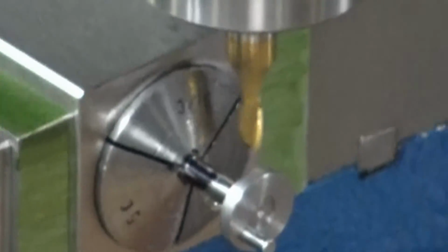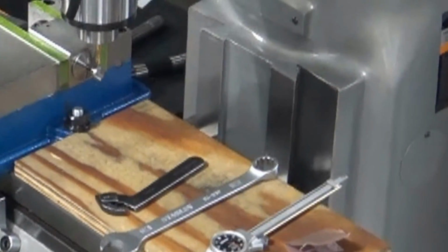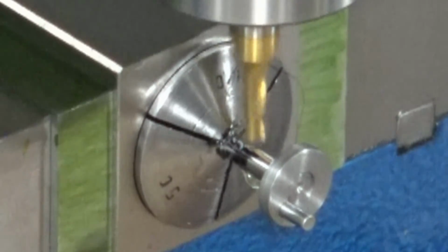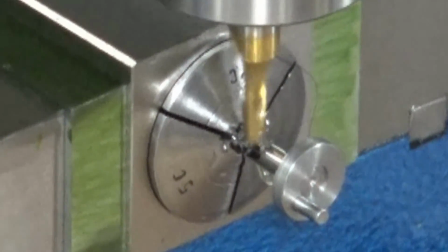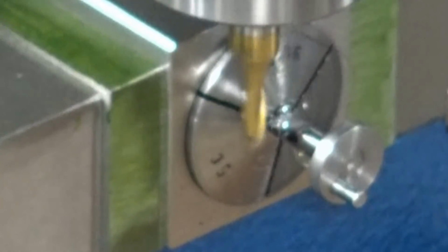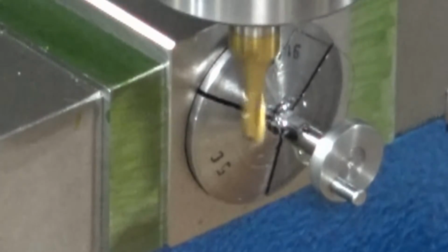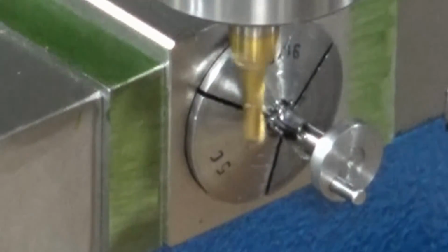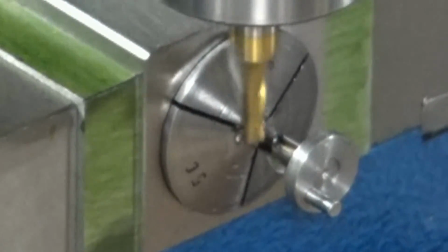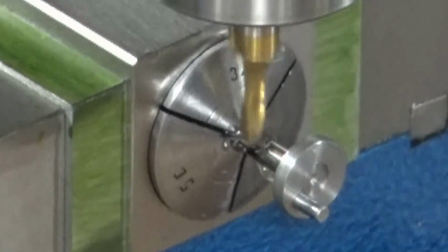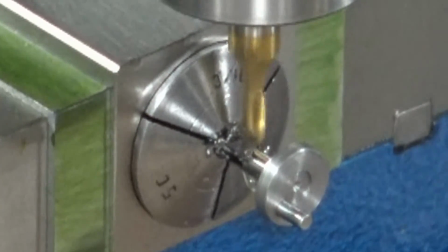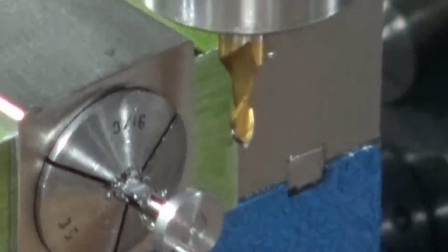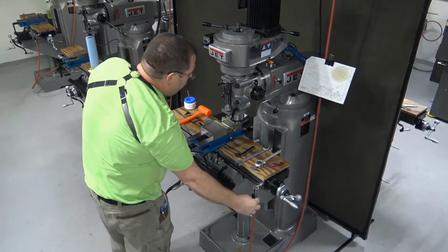The first step, I'm going to move down 15 thousandths. That's half the depth. I'm going to feed nice and gently across, okay? If it doesn't cut real nice, stop the spindle. There's something else going on. We fed all the way across. We're going to feed another 15 thousandths deep. So that's our 30 thousandths deep. Now we're going to back up, back through the slot. Okay. It took us a lot more time to set that thing up than it did to actually cut the part.